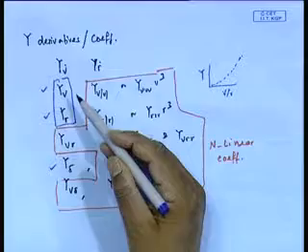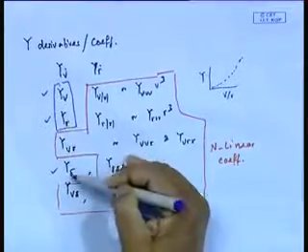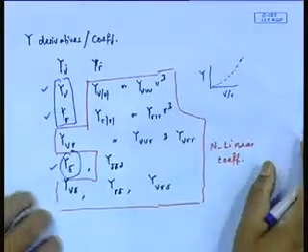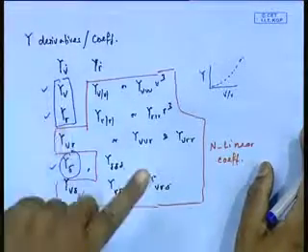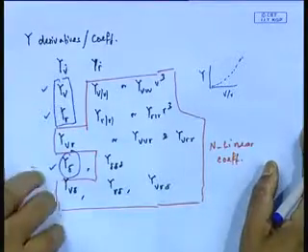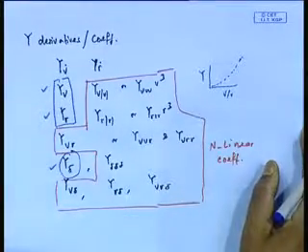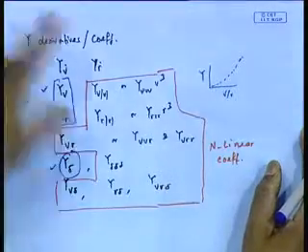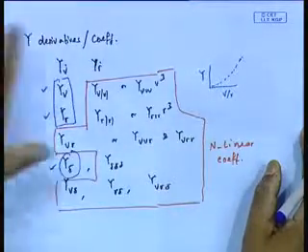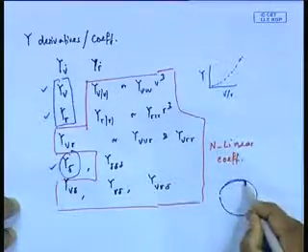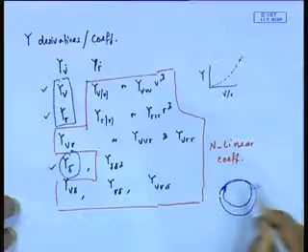Also, we have seen that for the turning circle, this and the corresponding n values are the ones that tell me the turning circle radius to the first approximation. You know, the turning circle radius, drift angle estimates, you want to make an estimate. Normally, you will find that if I use only linear derivatives, what I get, if I take nonlinear derivatives will be a tighter turn. That means, if linear gives me this kind of turn, nonlinear derivatives will normally give me a tighter turn.